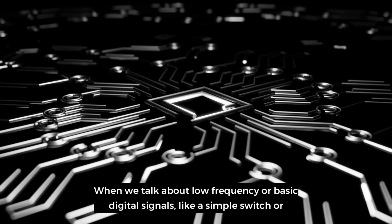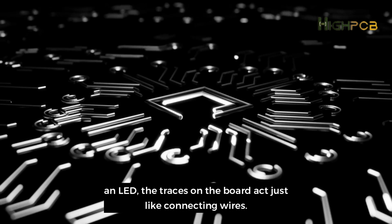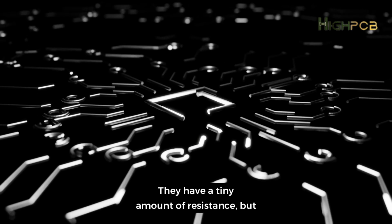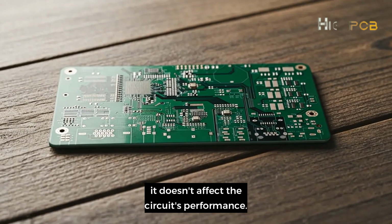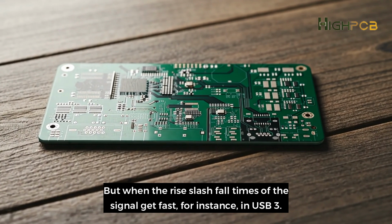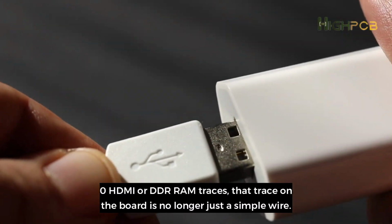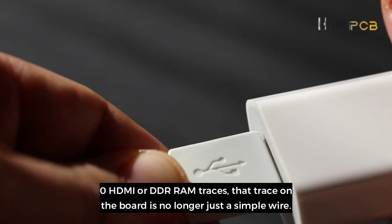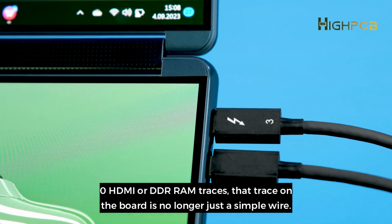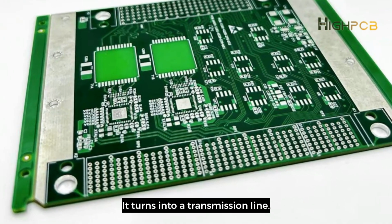When we talk about low frequency or basic digital signals, like a simple switch or an LED, the traces on the board act just like connecting wires. They have a tiny amount of resistance, but it doesn't affect the circuit's performance. But when the rise/fall times of the signal get fast, for instance, in USB 3.0, HDMI, or DDR RAM traces, that trace on the board is no longer just a simple wire. It turns into a transmission line.